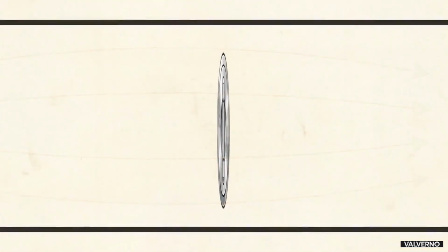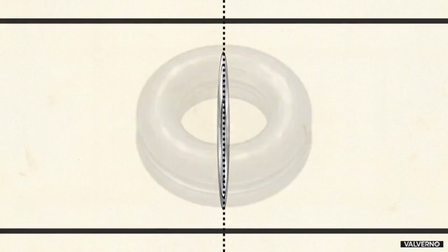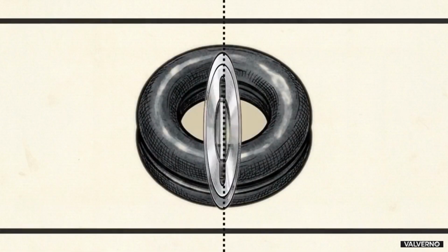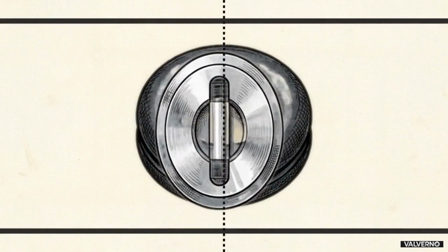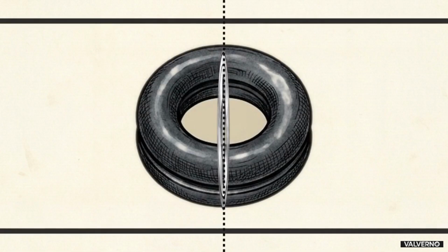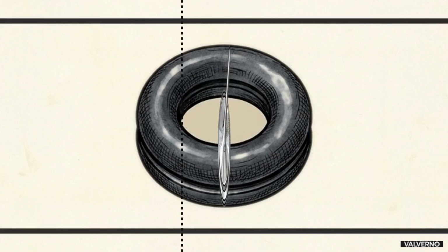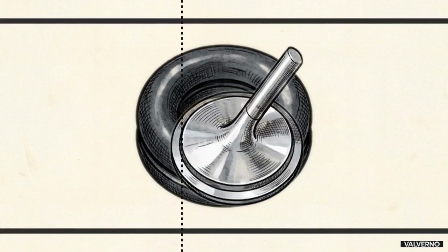The stem and disc are perfectly centered, compressing equally against a soft, resilient seat. This configuration works well for standard utility and low-pressure water systems. When system pressure and temperature exceed utility limits, you need the double offset design. Notice how the axis line shifts away from the center. This adjusted geometry reduces friction on the seat as the disc rotates, extending the valve's lifespan under higher pressures.